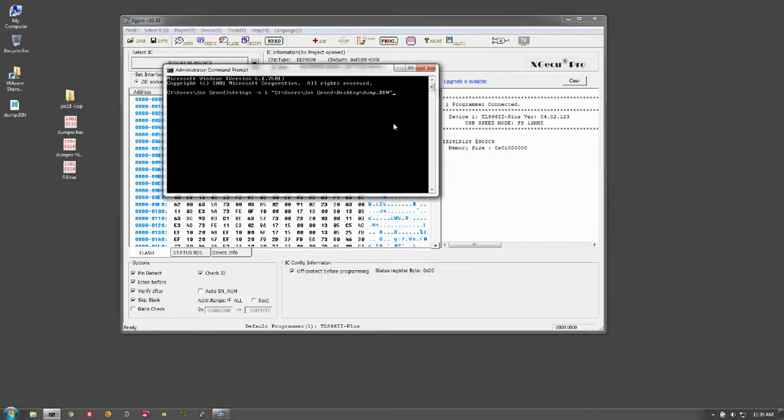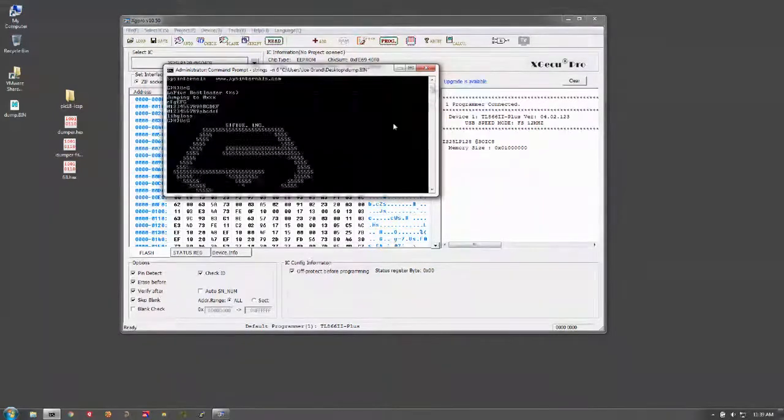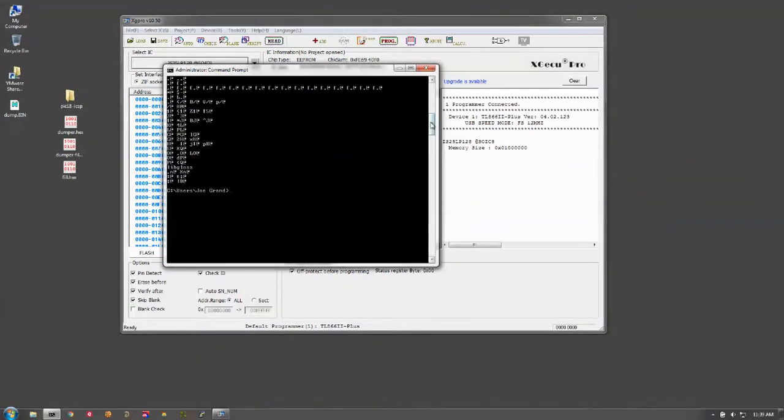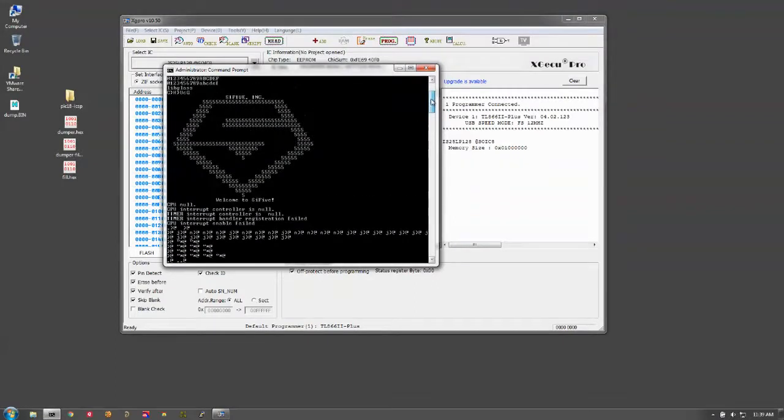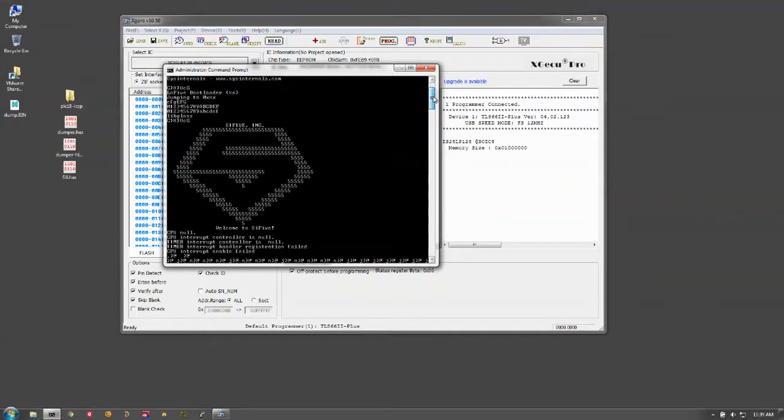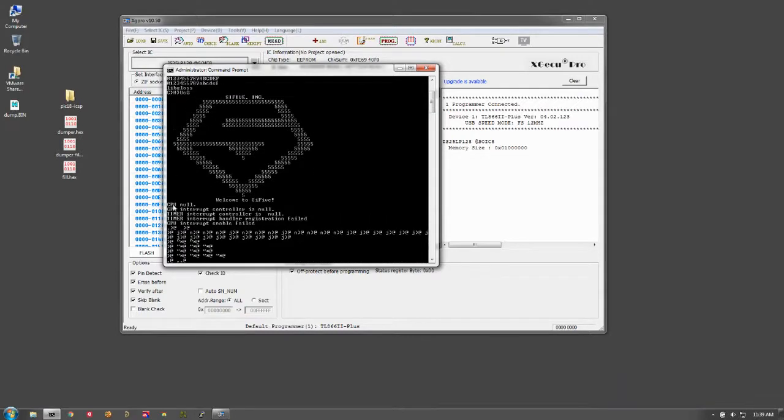So I can just drag that in, and we'll run strings, and it looks through that entire 16 megabyte blob and pulls out some cool stuff here. Lo5 bootloader jumping to whatever the memory address is. So this must be the bootloader stuff at the beginning of memory. And then this is the user code down here, this nice ASCII art logo. That's in my code when I had programmed these to print the logo and do some other stuff. It also has some debug messages.